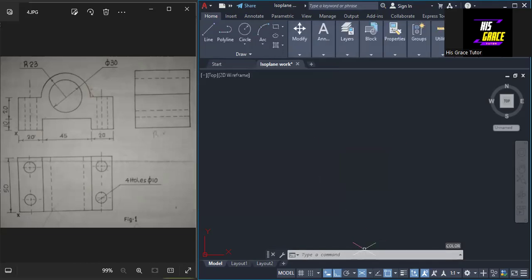Okay, so let's check where we are. We are on isoplane top, so let's change it to isoplane right. So we have this. This particular point is the lowest point X. I'm going to construct the whole of this base, without this particular shape, without this circle and without this semicircle. So I'm just going to construct it like this first. Let's see how it goes.